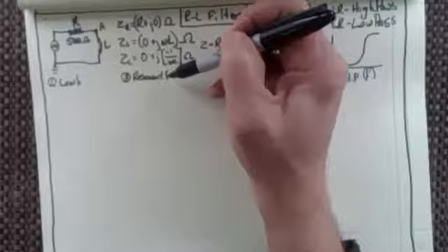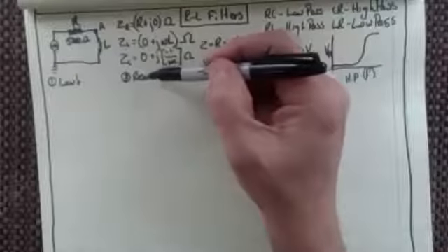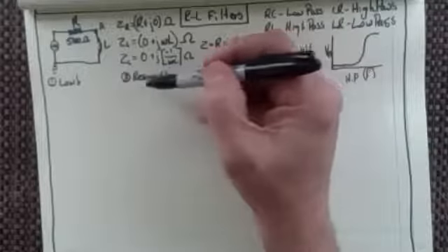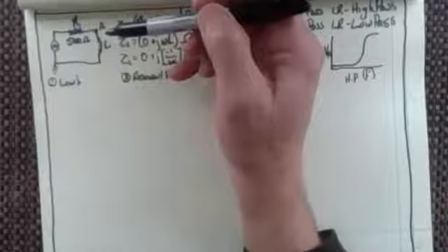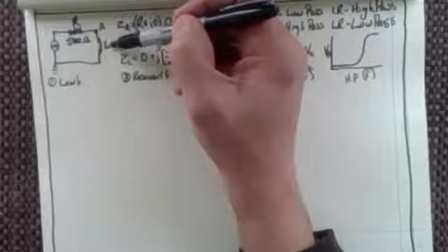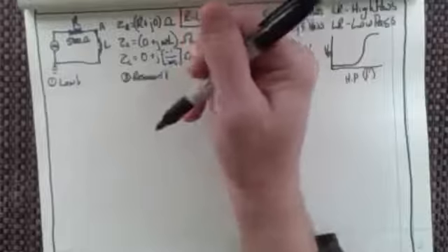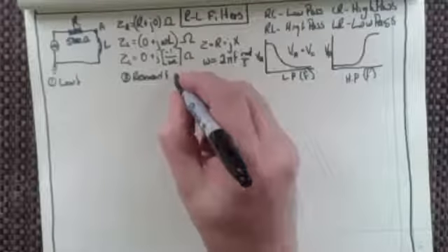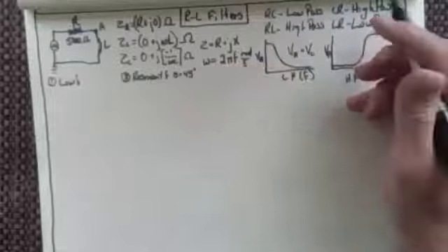The resonant frequency in a circuit is usually where you have an inductor and a capacitor, and the inductive reactance, which is positive, cancels out with the capacitive reactance, which is negative. That's real resonance. All I want to put here, and I should probably use different terminology, is where the phase shift angle is 45 degrees, because the resistance and the reactance of the inductor are equal to each other. The phase shift equals 45 degrees at that point, doesn't it?